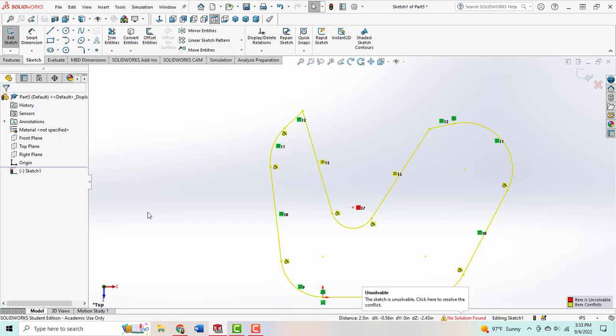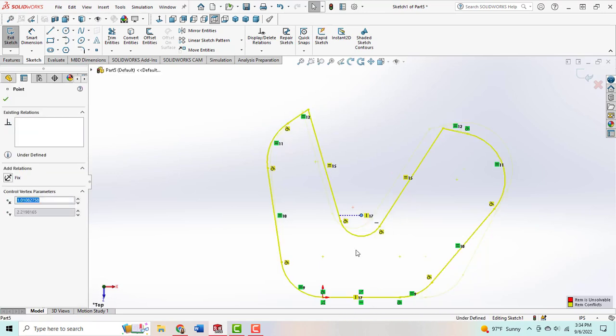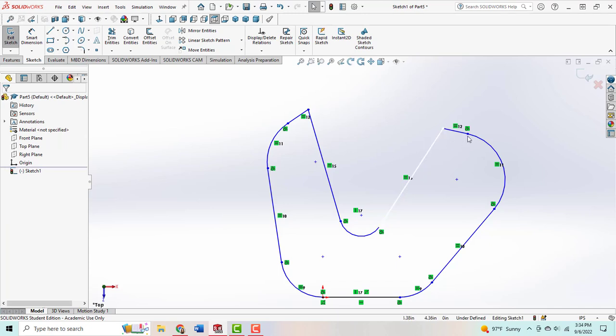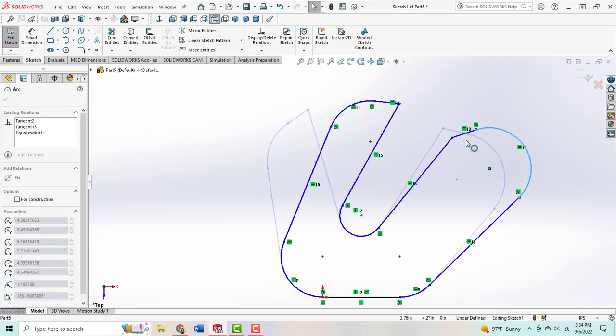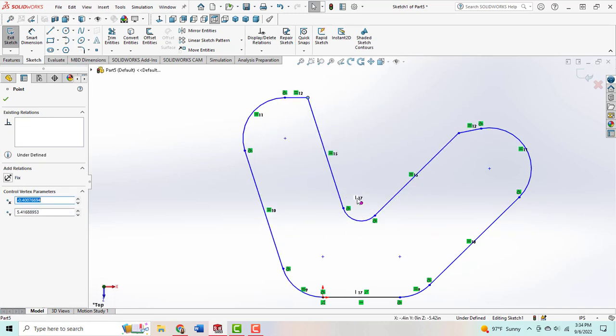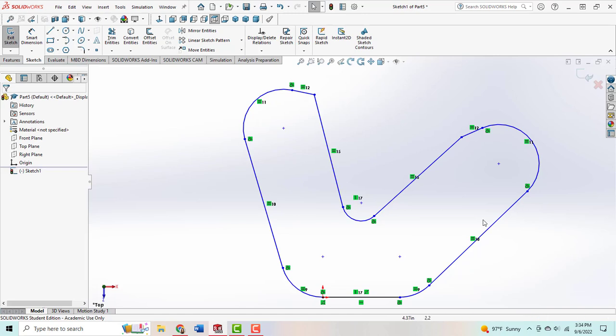I'm going to hit OK. As you can see, it is saying that my sketch is not working, because how I already had it set up and this side's so wonky, I don't have any dimensions or anything. If I just move it around just a little bit, it then lines up that vertical relationship. And I can see that here where it lights up those dimensions. So sometimes if it does pop up red, it's just because you need to move your sketch, or you can go in and double check all your relationships.